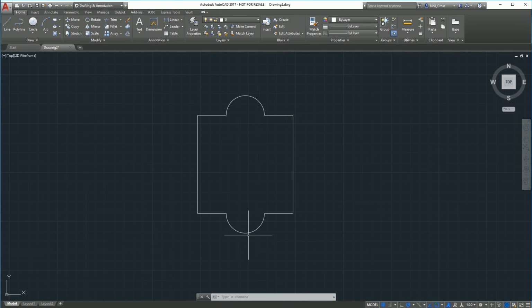For example, these two semicircle objects here, this one here and then this one here, if you intend for them to always be on a center line, well, back in the olden days of AutoCAD, you couldn't do that. The objects were completely independent of each other. So if there was a change in the future and this object needed to be moved maybe 50 mil across to the left or 20 mil across to the right, then this one here just stays put. But the design intent is that this one here should always be on a center line with that one. So you'd use a constraint to force them onto a center line, and then when you move one, the other moves with it. That's the whole point of 2D constraints.